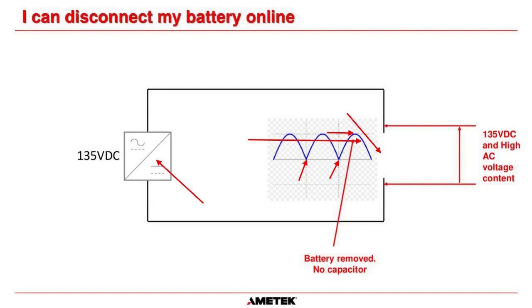So to say that you can remove the battery from a system and allow the charger to maintain the load is not correct in all circumstances. You have to be very, very careful when planning work on batteries if you know you have a charger that doesn't have capacitance in it.